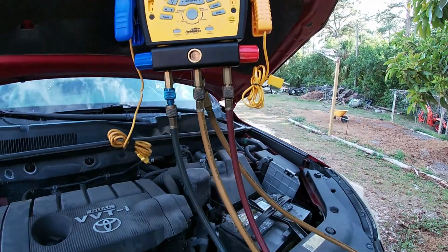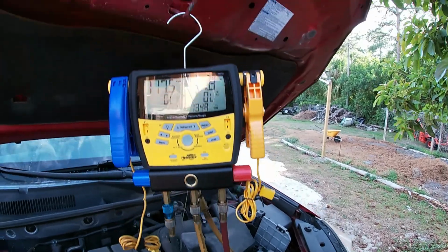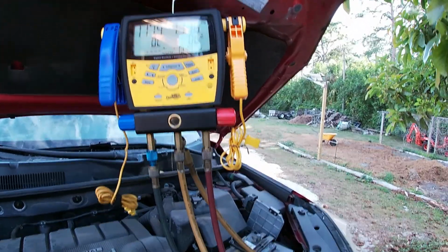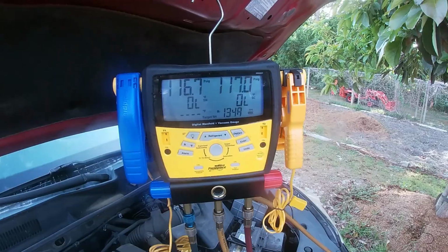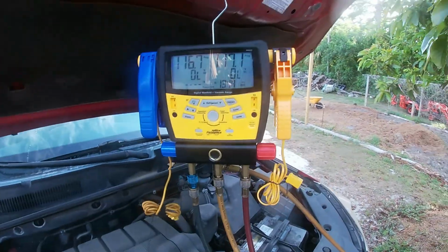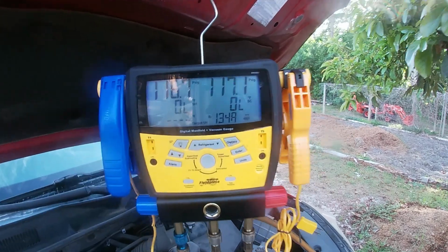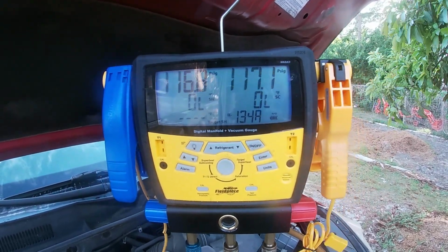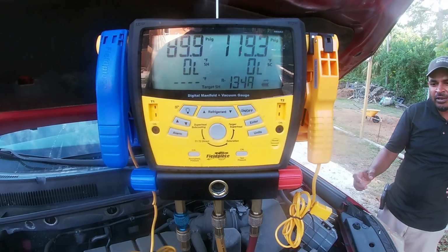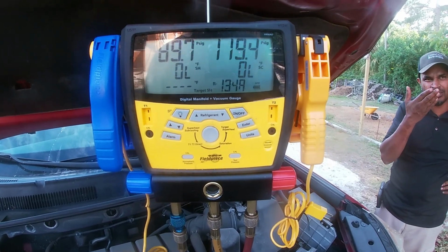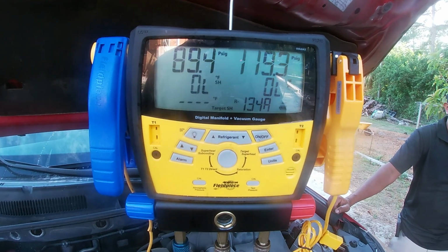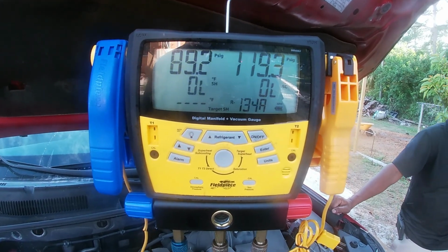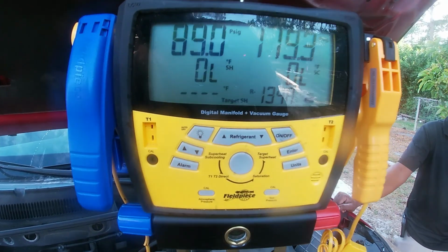Now what I'm doing here is that since I have all the tools for the air conditioning, I went ahead and checked the refrigerant level, to make sure it's operating the way it should. The highs are at the highs, the lows are at the lows, and I top it off with some refrigerant if it needed it or not. So that's the process I'm doing now to get him up and running back on the road.